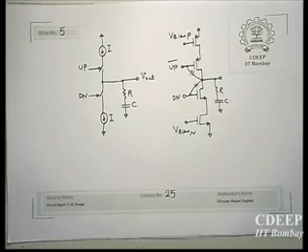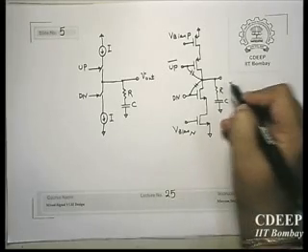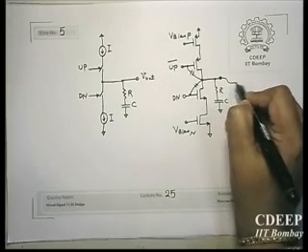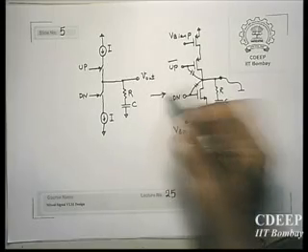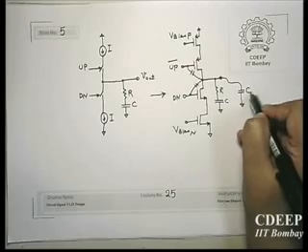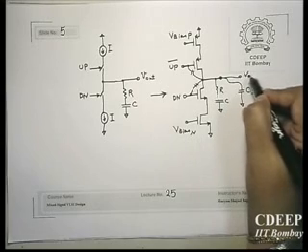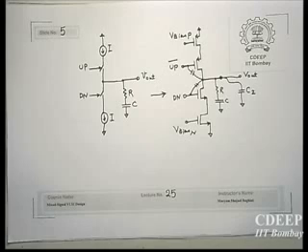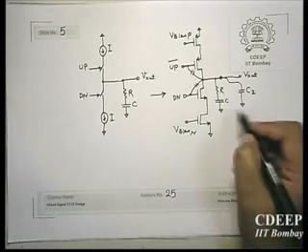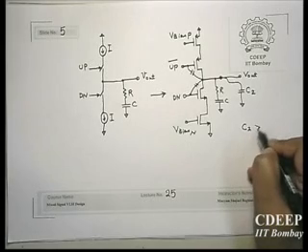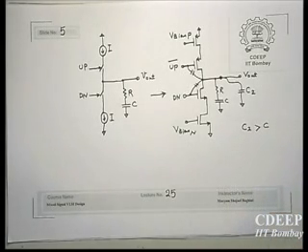So that's why usually people don't use a simple RC in a charge pump. They add one more capacitor here to avoid this clock feedthrough, any kind of spike which is injected here. Practically, of course, the value of C2 is larger than C. And therefore now you have one more C, which means your transfer function, which was second order, will now be a third order transfer function.